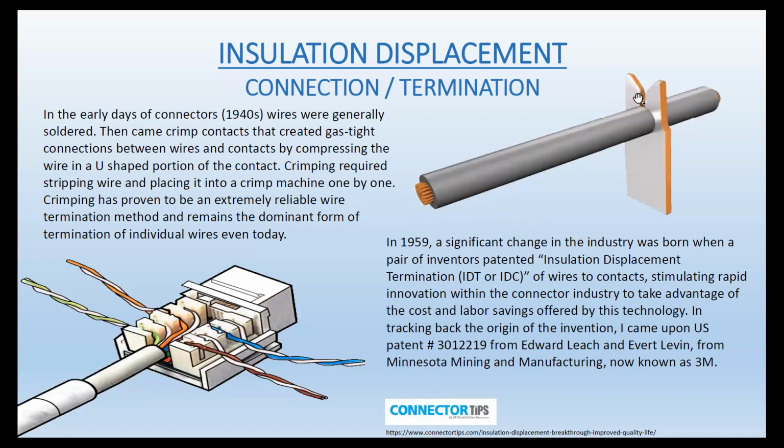Insulation displacement connection does not like stranded wire, simply because when you push that thing and those blades of the connector bite into that, they can actually cut some strands. So this is meant for a solid core wire, just so you know. And I left it there so I could talk about it.